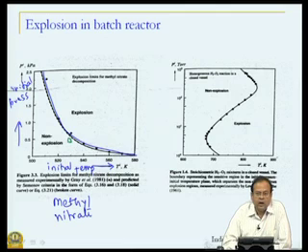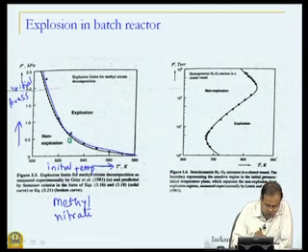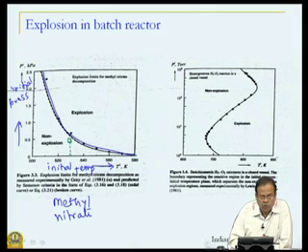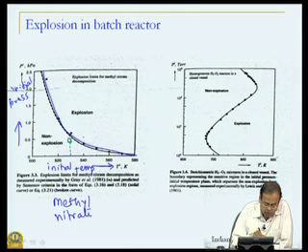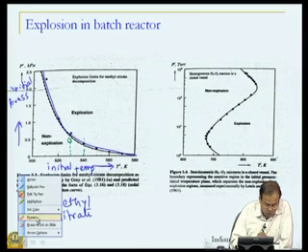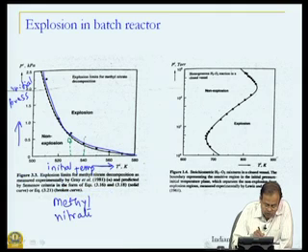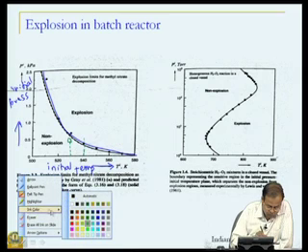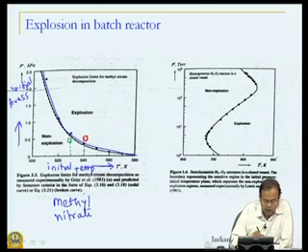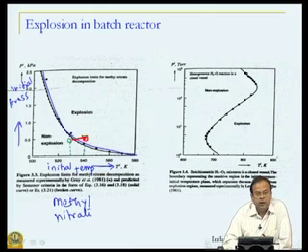I have no cause to be worried, but something happens at the start of this reaction, and temperature, which was supposed to have been at these levels, about 530 K, incidentally happens to be 540 or 535, same pressure but higher temperature. And now look at what has happened in our reaction. This is my new operating condition, and this is now in a danger explosive range. So, a small perturbation out of 500 K or 530 K, 10 is less than 2% error, but that can have disastrous implications for our reactor operation.